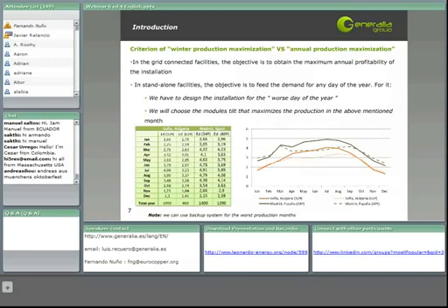So we need to produce and supply energy to our consumption by ourselves with this PV facility even in the worst period of the year. Obviously, we can help our facility with other mechanisms such as a backup system based on a diesel generator or any other kind of generator, but even if we do this, we have to consider the worst day of the year.